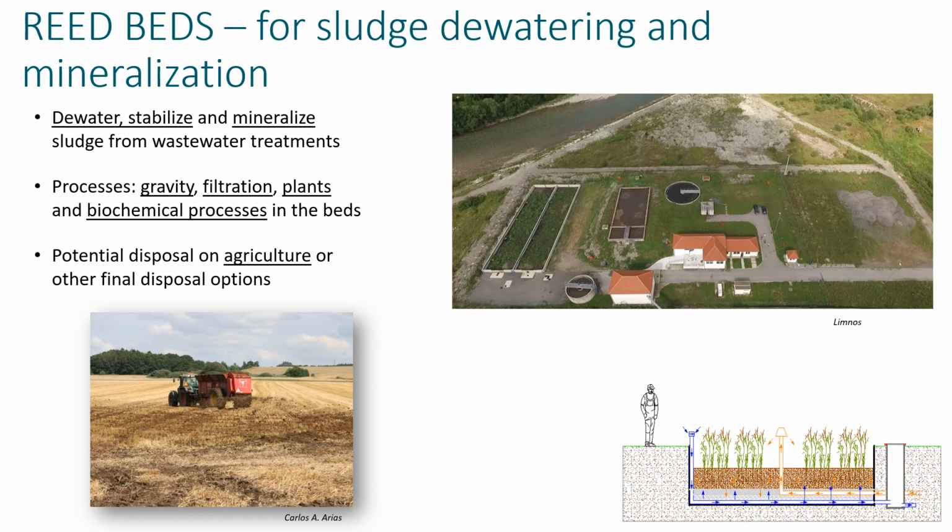The solid fraction of the sludge remains on the surface, while water drains out of the system through the filter media. The critical improvement of the planted bed over the unplanted bed is that the filters do not need to be dislodged after each feeding drying cycle. Fresh sludge can be directly applied to the previous layer. The plants and their root systems maintain the filter's porosity. It is expected that the reed beds can be in operation for more than 30 years.